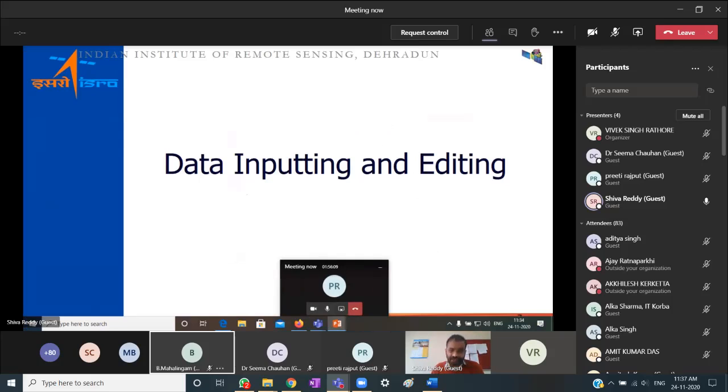So far we understand that GIS has two types of data: spatial data and non-spatial data, and non-spatial data is called attribute. For the spatial, we have seen that it has vector and raster, and vector data can be either point, line, or polygon. And any geographical phenomenon can be represented either as an object or a field. Objects are mostly represented as a vector, continuous fields mostly as a raster, and discrete fields we can represent as a vector or raster. So we move ahead.